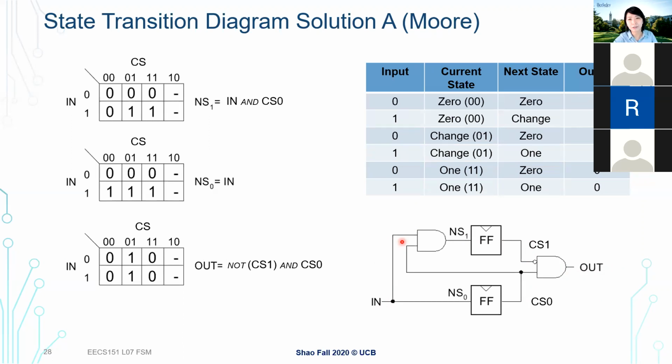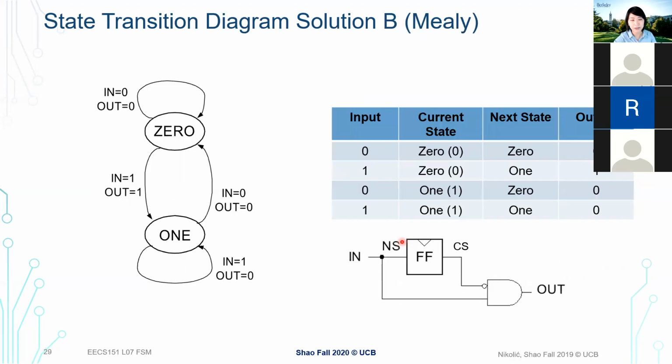And we mentioned that there is an alternative way, what we call the Mealy finite state machine. Let's go through this quickly, but we'll also talk a little bit more in the next lecture, so don't worry about that. So at a very high level, if you look at the state transition diagram, you may notice that instead of putting the output in the node of our state transition diagram, we're taking the output out as part of the edges. So my node only represents the states, but my output depends on the different input of my design. I may actually have different output.